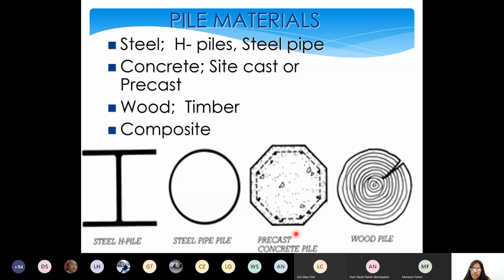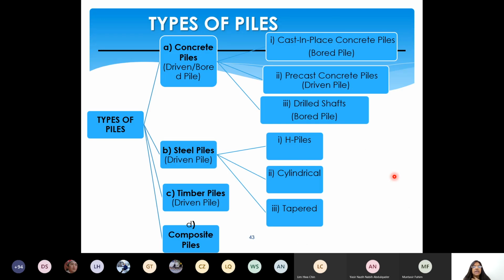And this is the casing, right? And this is the reinforcement. And between is a cover, maybe 20 mm, 2 centimeter, 3 centimeter, depends. And then the concrete is poured. Wood pile is like this, circular, right? One piece, and strength has to be checked before using.